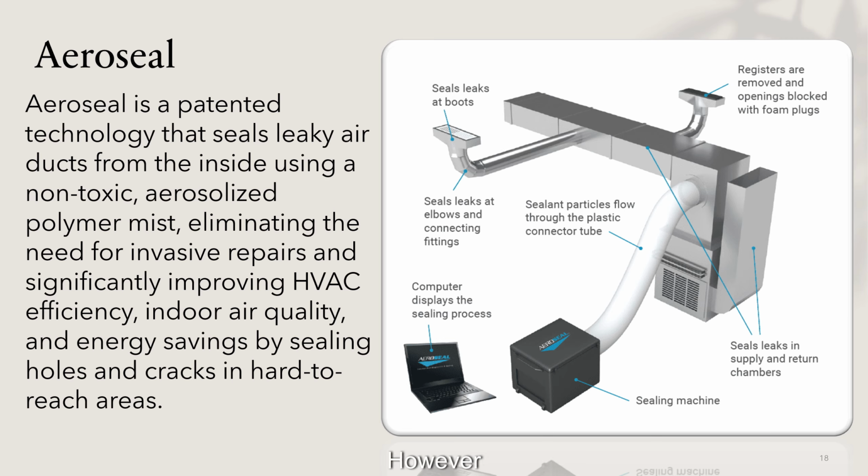However, one of the issues that I've encountered is that because ductwork is so poorly designed in our area, if you start sealing things up, your static pressure is going to start to increase. Our system had these leaky holes, and we set up our entire system based on that criteria.